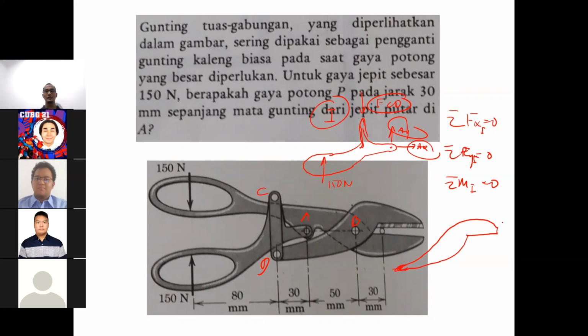Okay, what forces do we have there? There's supposed to be D over here and B over here. What forces do we have? FCD. FCD is supposed to be going down or up? Here down. Are you sure? Up, yeah, it's supposed to be action and reaction. Actually, it's based on your results of the first free body diagram.